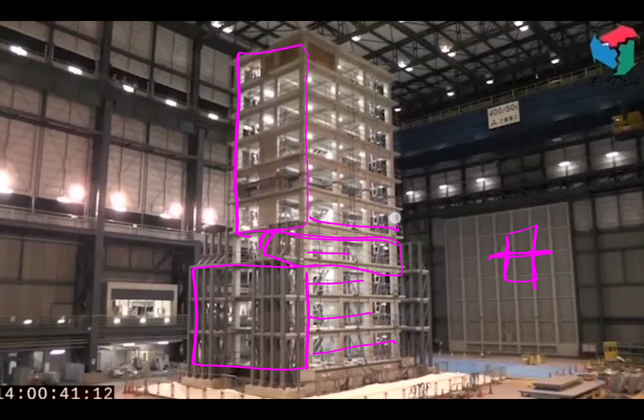And the fourth floor is the one that acted like the columns on the first floor, the other structure we saw. When it whipped coming back, this part is the stable part. Whipping this over left and right creates stress and strain in two directions on this one, and that's where you get your fractures.